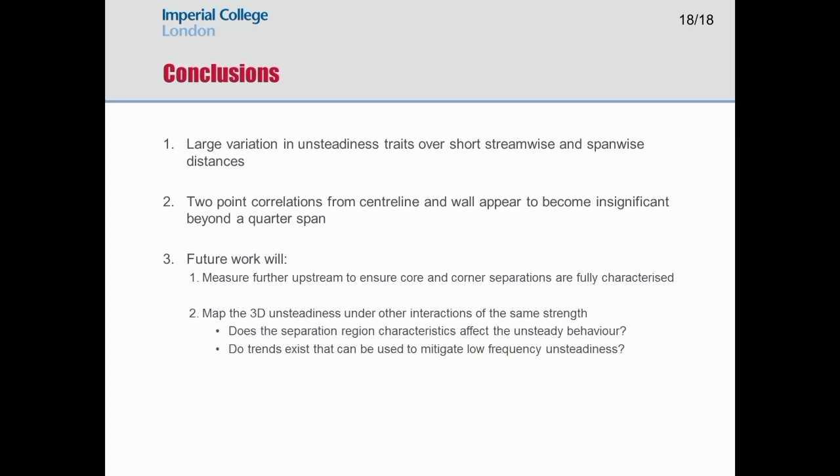Any questions for Paige? Does the injection hole of the oil not affect the unsteadiness? It's a good question. For each case I do 2 runs. There's a hole in the center and some off-center holes. So I do one run injecting through the center and a separate run where I inject at a quarter span, and I see the same patterns. The hole itself might have some effect. It doesn't have zero effect for sure, but I don't think it massively affects where the flow is separating.